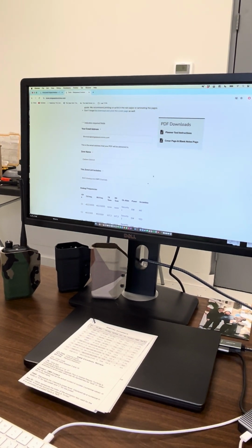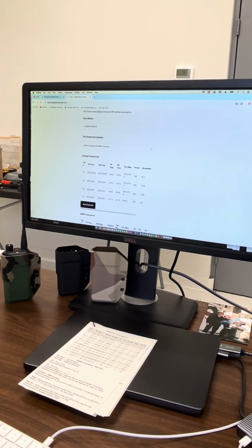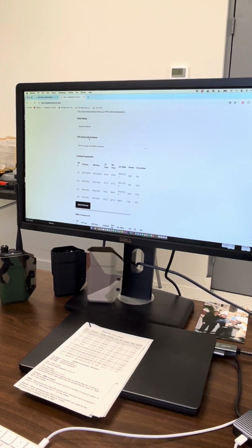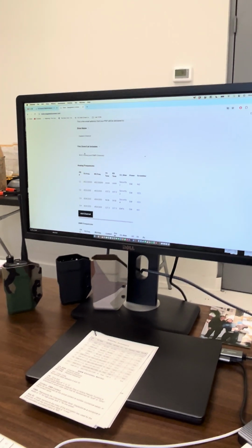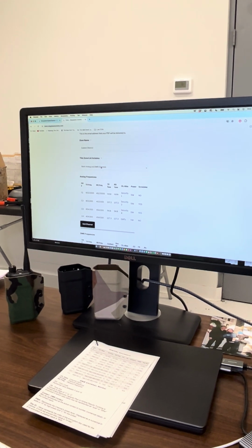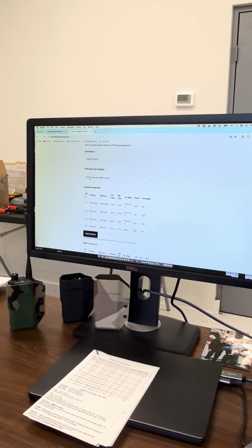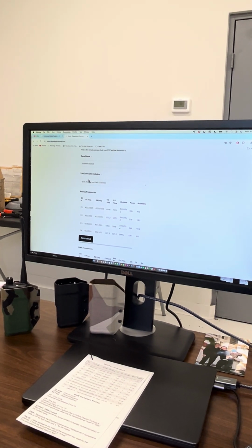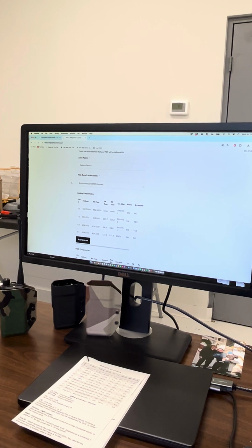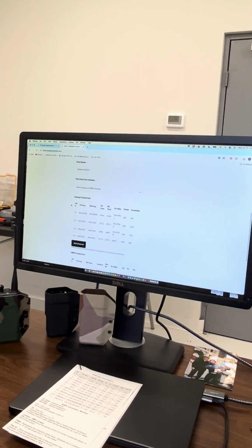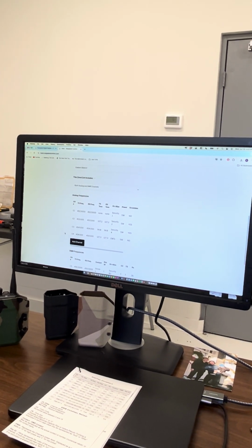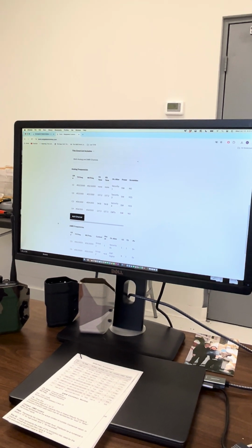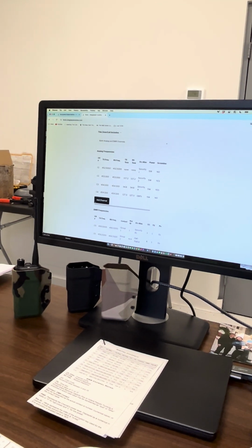As you'll see, I've already started on one just so we have something to work with, but you have the option here to determine what you want to make. So you can make zone lists for, in this case, both analog and digital channels. You can do them for a zone just for analog channels, just digital channels, and you can also do a DMR contacts list. So let's go ahead and create an analog channel, and we'll show you how this works. We'll do an analog channel, a digital channel, and then we'll print it out and show you how it comes out.